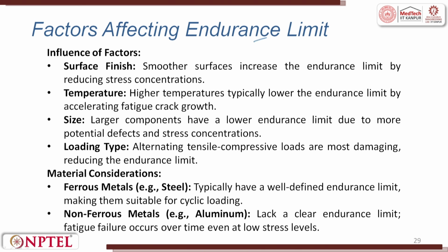What are the influencing factors for endurance limit? The surface finish plays a very important role. If a surface has roughness, wherever there is a dip, there is a possibility of a crack to grow. A smooth surface increases the endurance limit by reducing the stress concentration points.